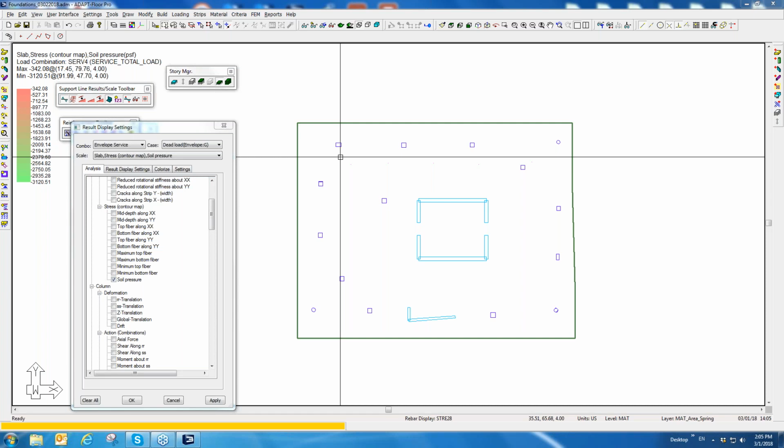Earlier I said you can either model piles as columns or you can model piles as point springs. If you model them as point springs, it won't check that punching. If you model them as actual physical components, then it would check the punching for the piles. And if it gives you exceeds code, that just means that the shear stress that the program calculates at that column exceeds the maximum allowable shear stress for whatever code it is you're using.